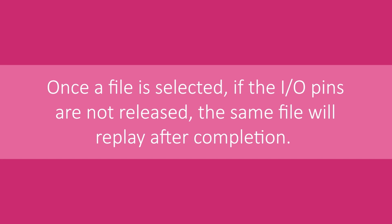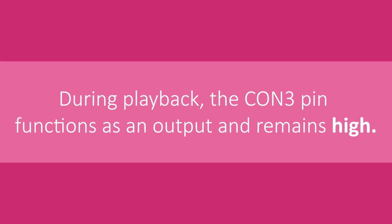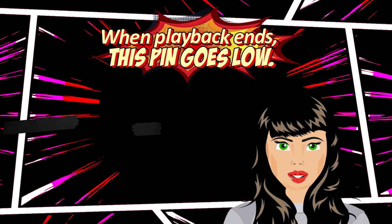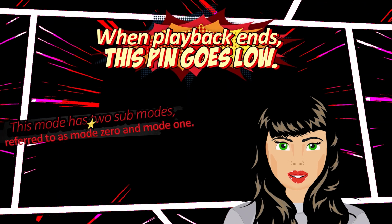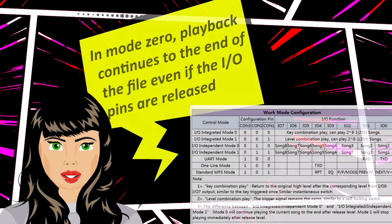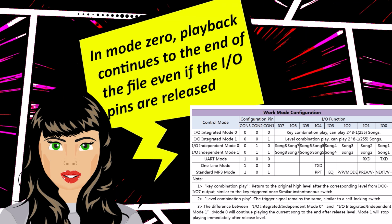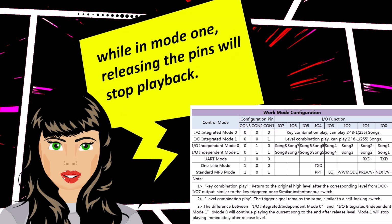Once a file is selected, if the I/O pins are not released, the same file will replay after completion. During playback, the CON3 pin functions as an output and remains high. When playback ends, this pin goes low. This mode has 2 sub-modes referred to as Mode 0 and Mode 1. In Mode 0, playback continues to the end of the file even if the I/O pins are released, while in Mode 1, releasing the pins will stop playback.